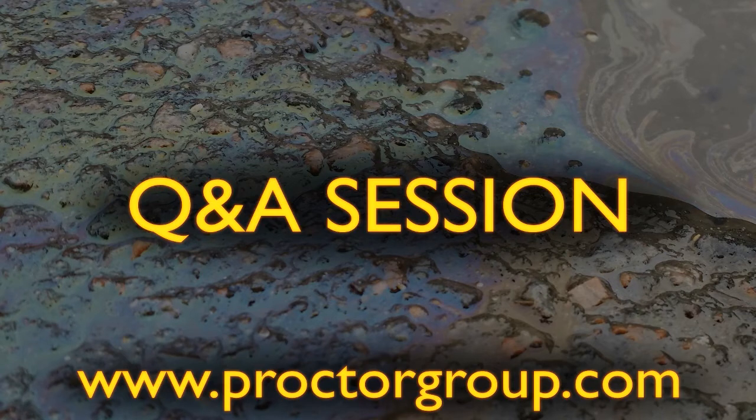Great. The first one I received was regarding the use of foil membranes in VOC applications and whether that's suitable or not. Yeah, as we said in the webinar, there's a common misconception that they can be used when dealing with hydrocarbons in a gaseous state. However, depending on the concentration and the type of hydrocarbon, these foil membranes can easily oxidise due to the exposed cut edges, and the amount of protection they give from hydrocarbons will be dramatically reduced in that case. So you should really look for a proper VOC membrane.